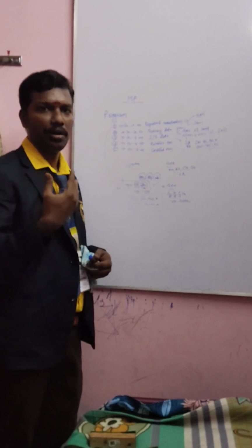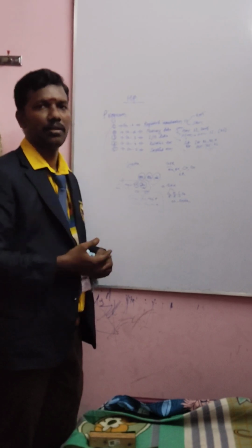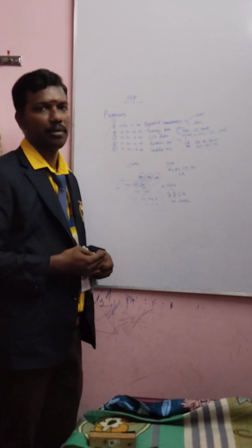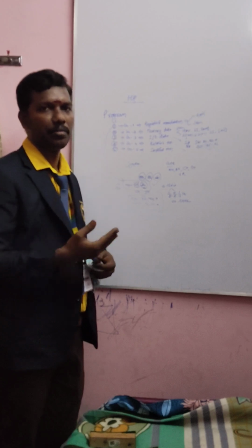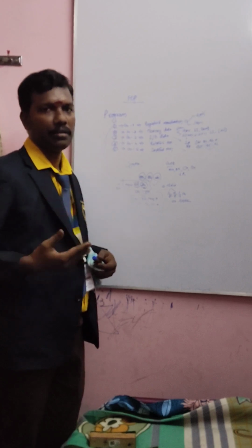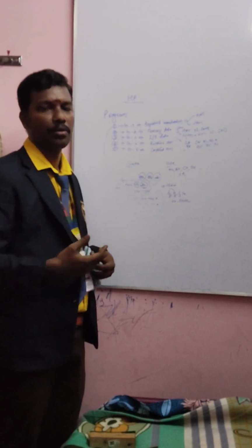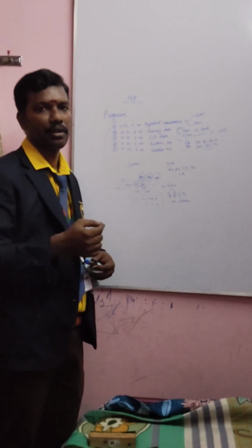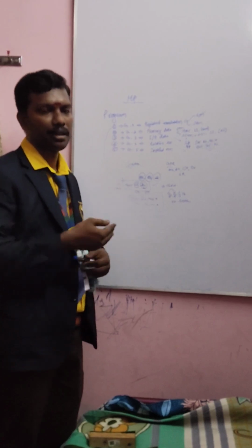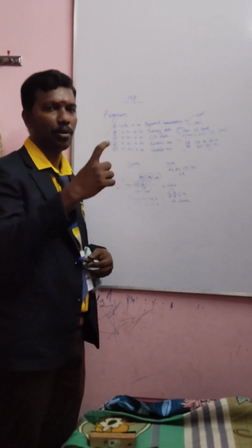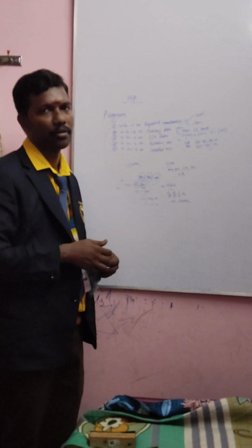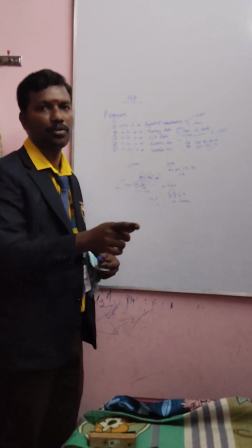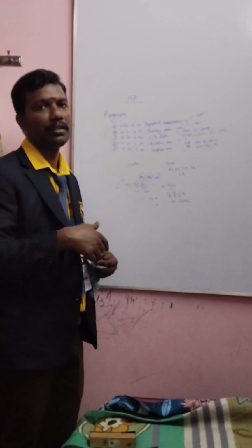If you're going in a very fast manner, 1 or 2 will be there, or if you make it step by step, it will be 90 degrees, A, B, C, D, like A1, A2, B1, B2. Likewise, you make the winding go in the clockwise direction or anti-clockwise. So for that, we are going to keep some data. Initially the program will be continuous, for making how long you are going to do it, how fast you are going to do it. How long is represented using the array, and how fast is measured in the lookup table.